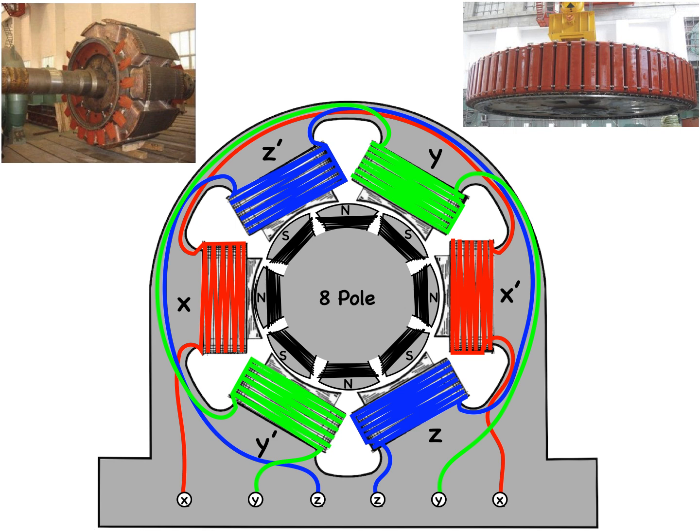These salient pole rotors allow for better ventilation. The pole faces are so shaped that the radial air gap length increases from the pole center to the pole tips, so the flux distribution in the air gap is sinusoidal in shape, which will help the machine generate sinusoidal outputs.